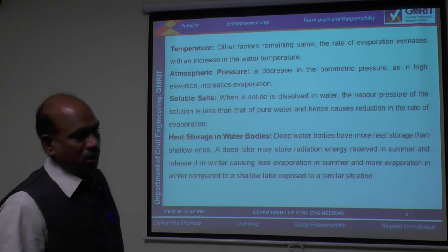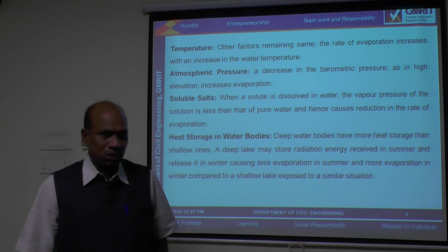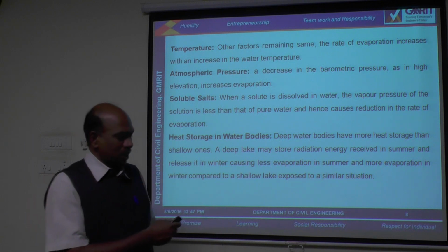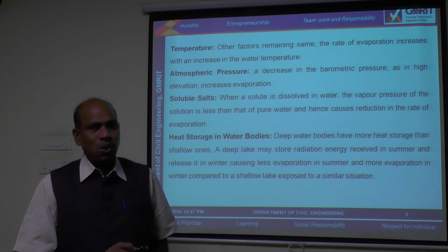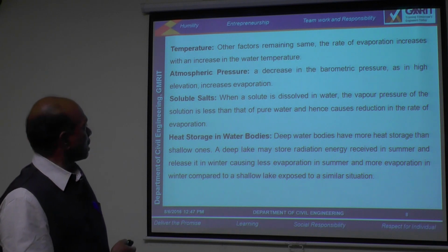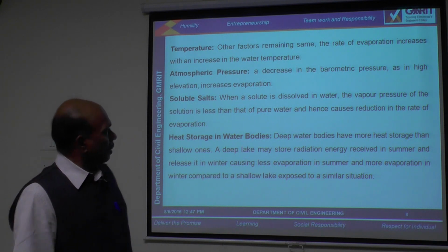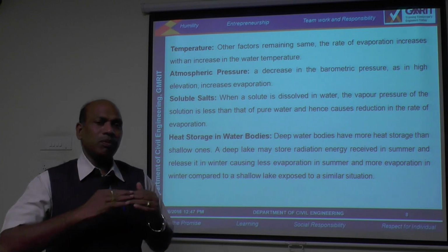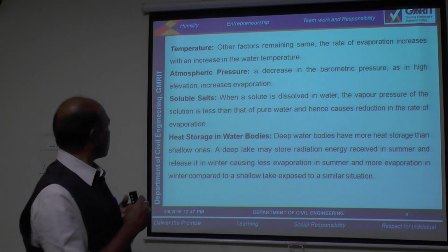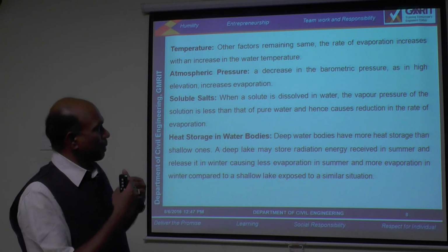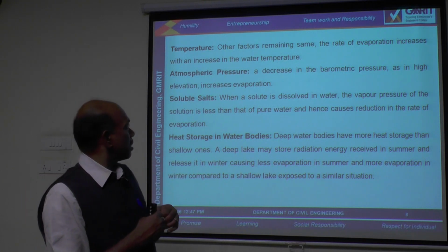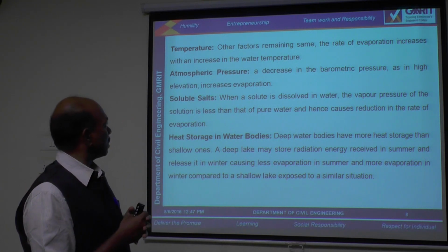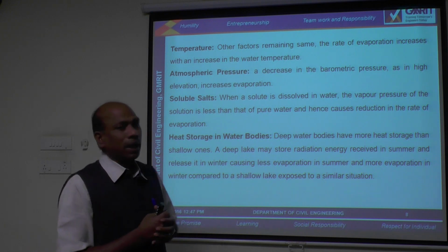Then temperature, this is another factor. This is known to all, that as the temperature increases, the evaporation rate also increases. And atmospheric pressure also varies with respect to level. At high elevations, the atmospheric pressure, the barometric pressure, reduces automatically. In that situation, the evaporation rate will increase.